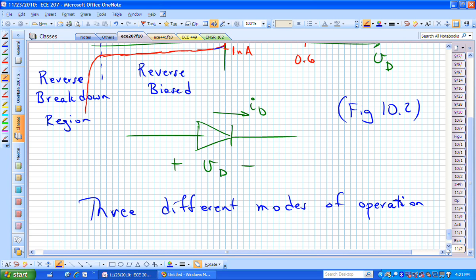So it's really not turning on or opening that valve, so to speak, until you get beyond 0.6. Once you get beyond that, it's going to really allow the current to flow very easily, and you can then have a 0.6 voltage dropped across this diode and have as much current theoretically flowing through it as possible.